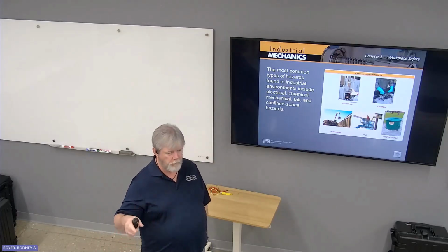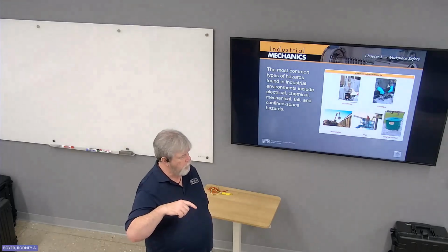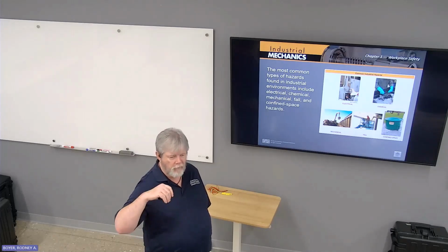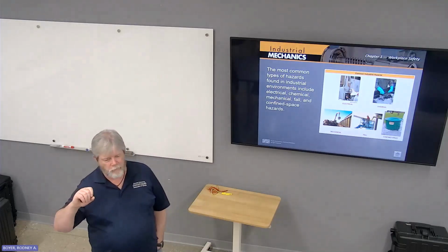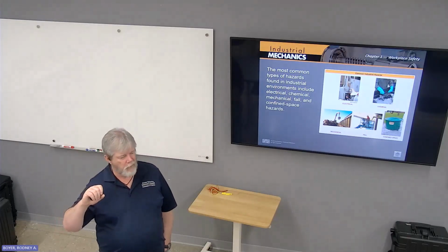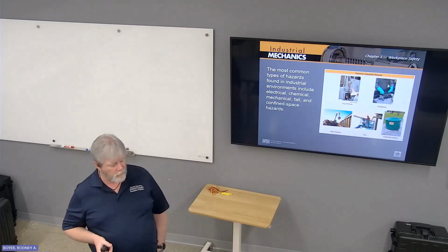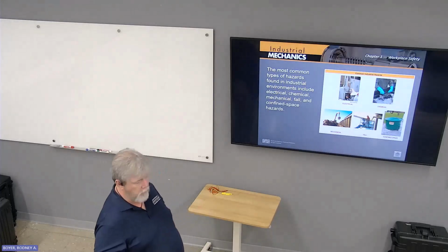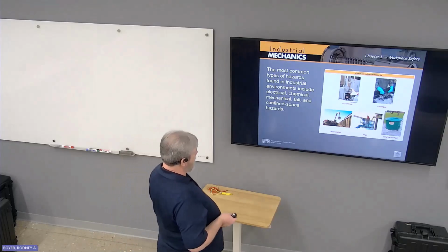There are exceptions to that where if you're on a scaffold, you have to be at least 10 feet off the ground before you have to have fall arrestor. Understand what the difference is between 4 feet and 10 feet. You're still gonna fall and break your arm or land on your head and kill yourself. And then confined space.